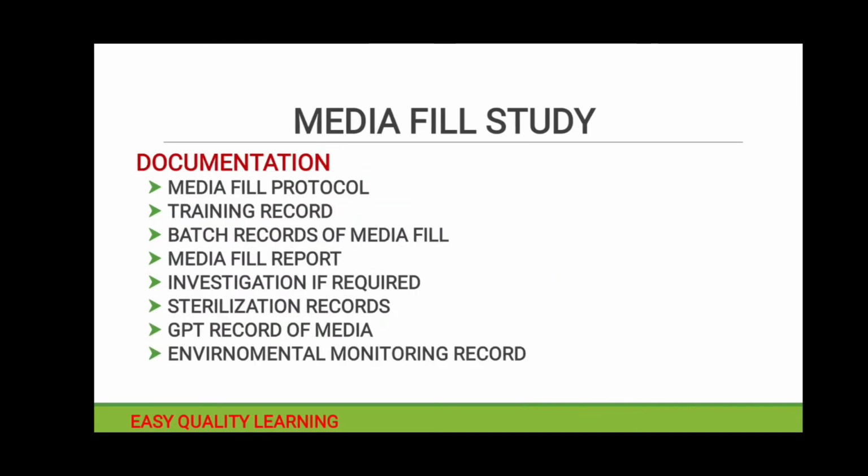Then, what should be there in the documentation? Naturally the media fill protocol will be there, and the training record shall be enclosed with the media fill protocol. Batch records of the media fill which we execute should be there. The media fill report shall be prepared based on all these activities. If we find any failure, then the investigation report shall also be enclosed along with the media fill report. Then sterilization records, for sterilization of containers, closures, and machine parts, all need to be included along with the report.